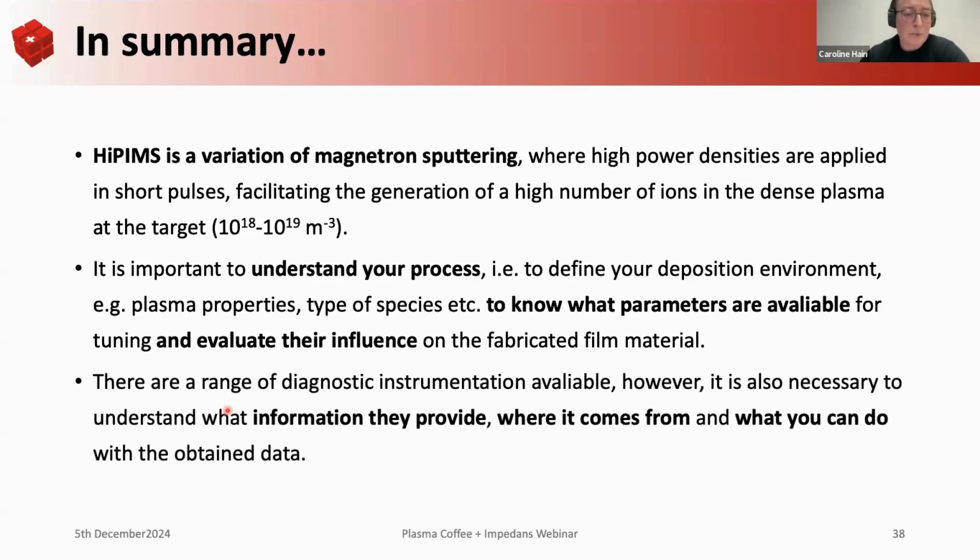And there are many diagnostic tools available. Some of them I mentioned. There are others that are in situ, linked to characterizing the film, like in situ ellipsometry. You can do in situ stress measurements. But it's also important to understand what information you can gain from them, where this information comes from, where we get the numbers from, and what you can in turn do with the data and how you can apply it to your process.